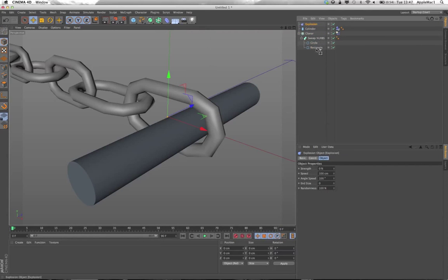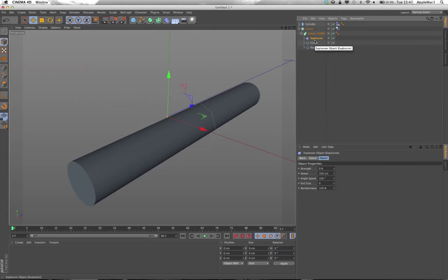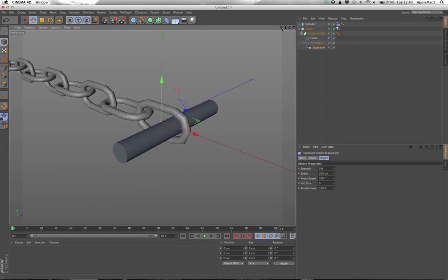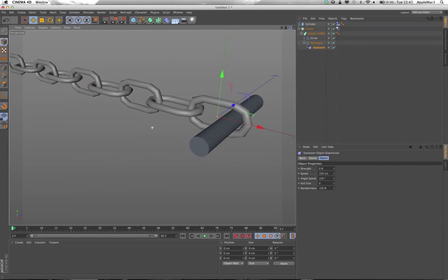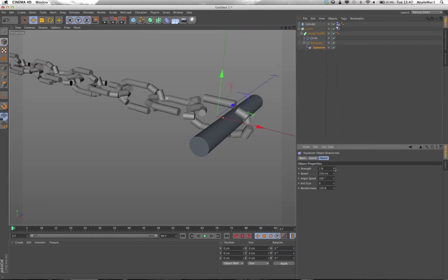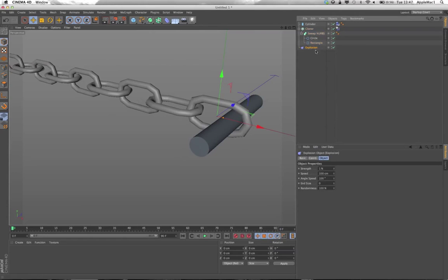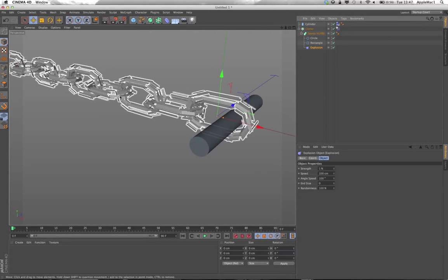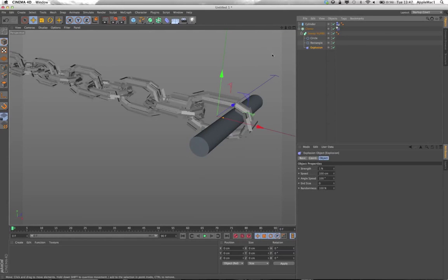So we're going to drag it below the rectangle. If you put it in here, it messes up the sweep NURBS. If you put it at the bottom, it can work with the sweep NURBS. The value is at 0%, so it's not done anything. If I up the strength of the explosion object to 1%, you can see what happens, and that is not good. I've actually added that to the rectangle. I wanted to add it to the sweep NURBS. So 1% will do this, which is not what we want, because it's exploded it way too much. So what we can put in the value here is 0.01.